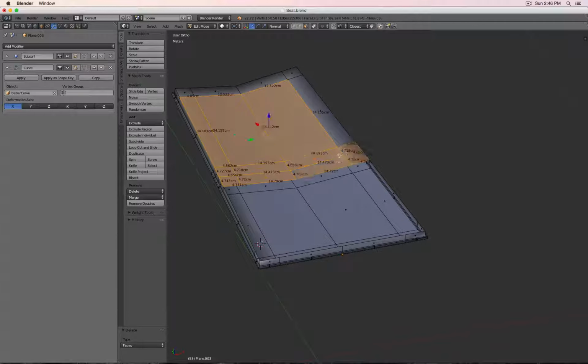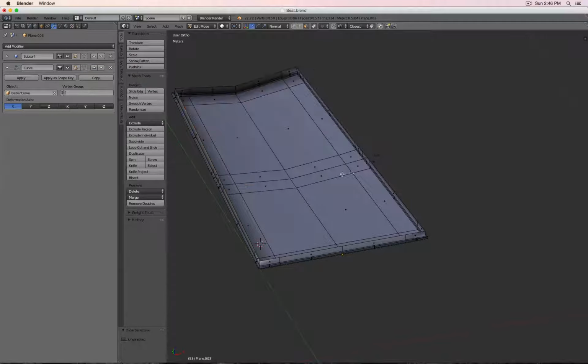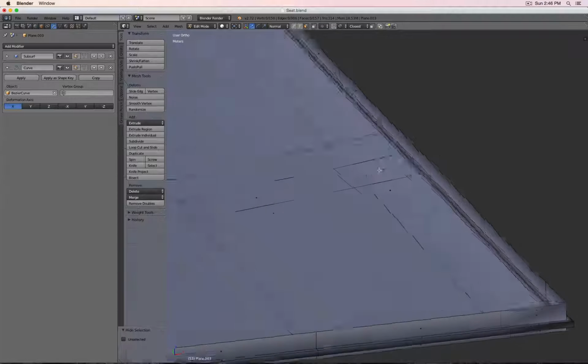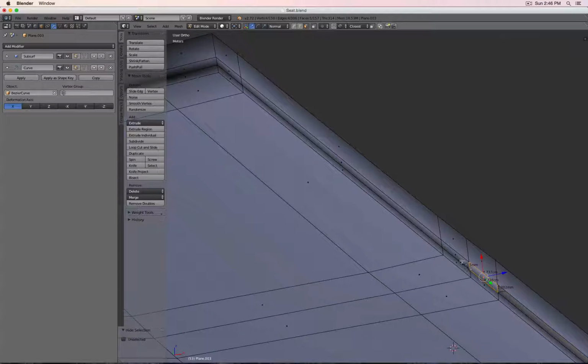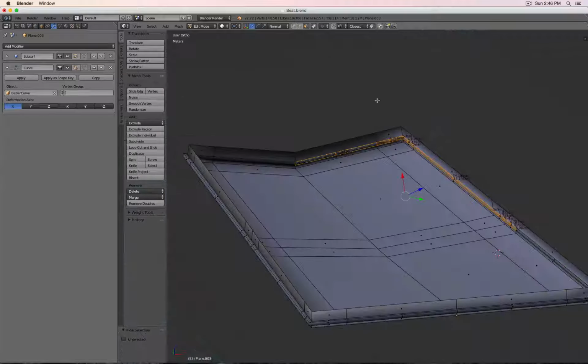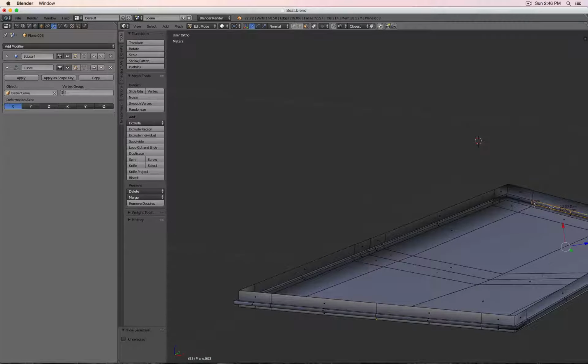So let's paint those and height. And I have my key shortcuts changed, so currently my shortcut for selecting the loop cuts doesn't work, and you of course can do this by pressing Alt and clicking on an edge horizontally or vertically, and then that selects the loop cut.